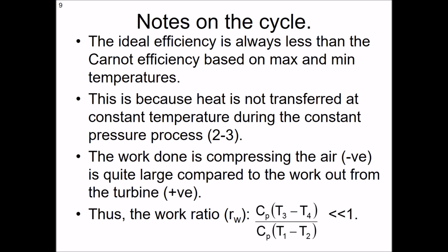They don't work on a wonderfully theoretical basis like the Carnot cycle. They're practical systems. So although the numbers don't look great, when they perform in real life, they're actually very, very good. They're extremely efficient. So work ratio would simply be the energy between what the turbine's doing and what the compressor's doing, which we can see by the formula there.